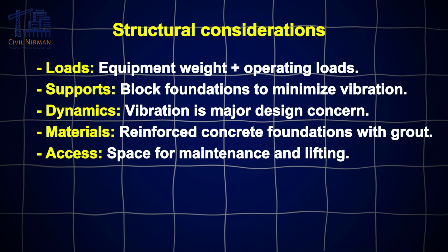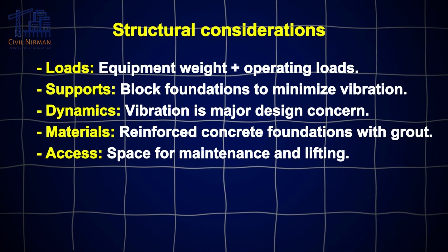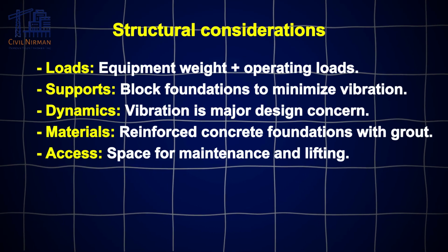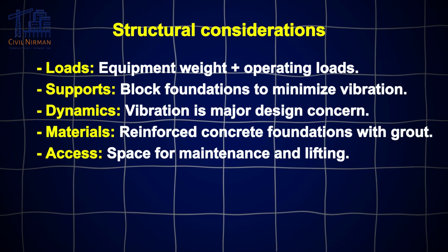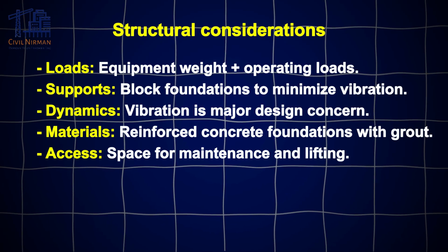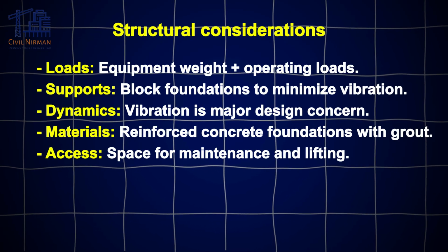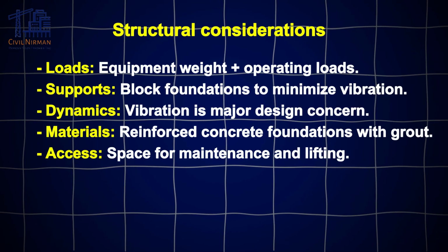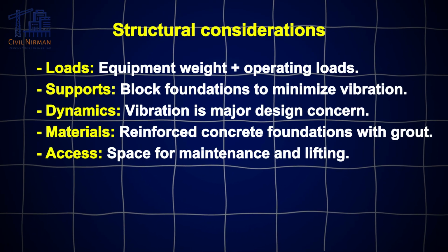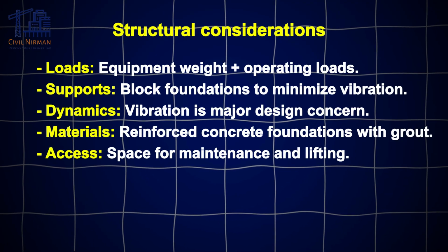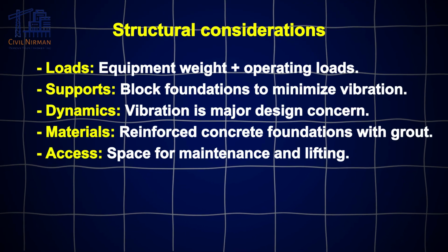In case of their structural consideration, we have to take care of the entire equipment weights in terms of empty, operating, high rotation, and the other loads. Usually they are supported on block foundations to minimize the vibration. In case of their dynamics, vibration is the major design concern, and they are usually made up of reinforced concrete foundation with the grout specification. For their access, space for maintenance and lifting is required.